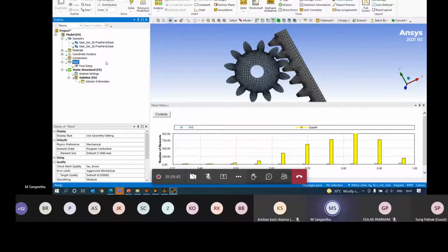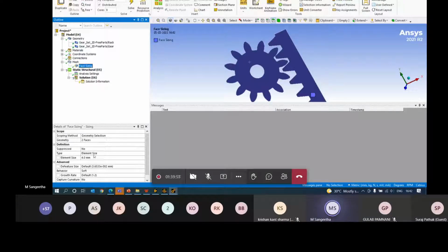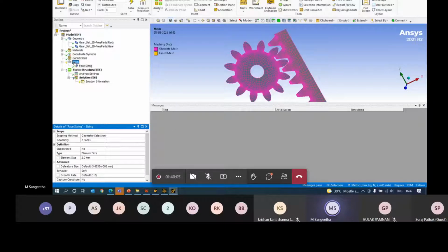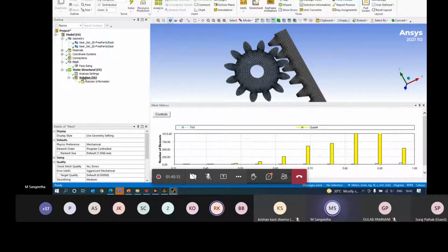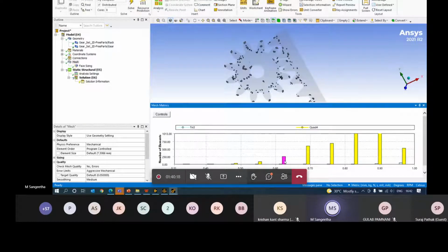So whenever you're trying to work with the mesh, it's always about looking at your element quality and then improving, because it will give you an idea where exactly you have to work on your mesh, right? So you can see here 4 doesn't work out for us, so we need to go with something less. So this is just to show you other advanced techniques. We'll check it out. Right, so however much you do, it's not ready to improve its quality near the edges, right?